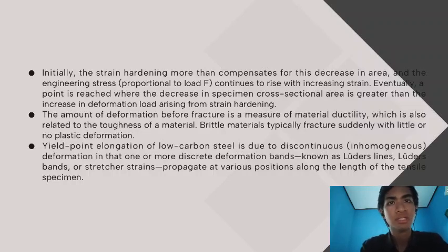It should be remembered that engineering stress is normally the nominal stress rather than true stress. In the initial portion of the plot, the amount of lateral contraction of the specimen is distributed along the entire test length of the specimen, and is therefore so small that the nominal and true stress are almost identical.